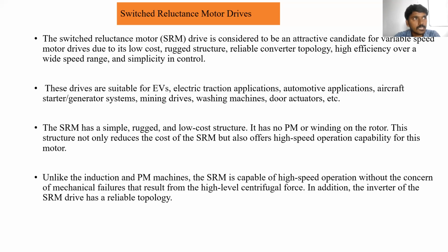We just design the rotor, made of laminated steel material or iron core, in order to form poles. Here we are not using any extra electromagnet. That is a small difference. Remaining the same, the operating principle and construction are the same as a brushless DC motor.